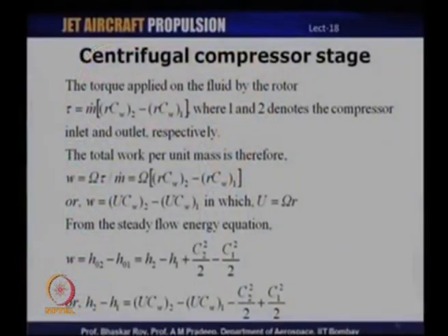So, having understood some of the basic aspects of centrifugal compressor, what we will do now is to see if we can analyze a centrifugal compressor rotor in some way. We have already done this for an axial compressor rotor. So, we can try to analyze the performance characteristics of centrifugal compressors, and let us see how we can do that based on the geometric parameters like the blade speed and radius and so on. So, the first thing that we will do is to relate the enthalpy rise across a centrifugal compressor to the geometric and velocity parameters.